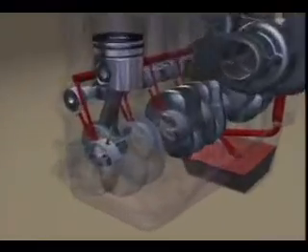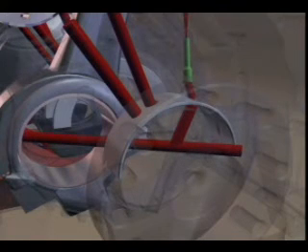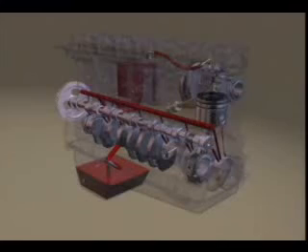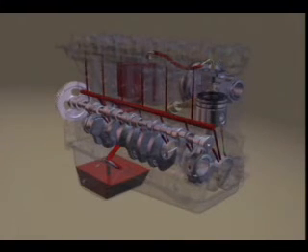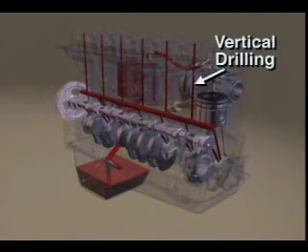From the main bearings, oil enters the crankshaft and lubricates the connecting rod bearings through internal cross drillings. Oil to the overhead is carried to the cylinder head deck by individual vertical drillings, one per cylinder, intersecting the main oil rifle. The oil then flows to a drilling in the cylinder head.